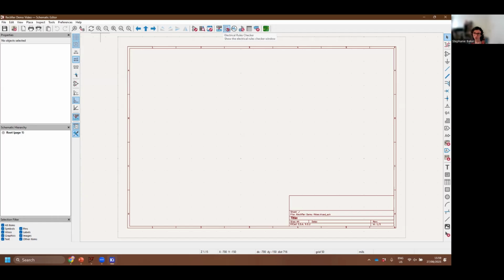One tool that can be useful is the electrical rules checker, and that just allows you to check that everything's electrically connected and valid. There's also actually a Spice simulator built in that you'll see. It's really clunky though, so simulate everything in LTSpice and then move over to here when you're ready to actually build a PCB. And then what we'll eventually also use is the PCB editor, where we generate our physical board based on our schematic.